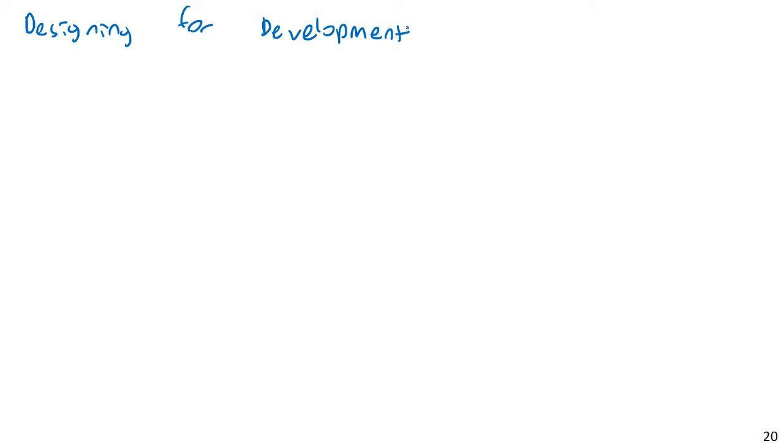We're going to spend most of our time talking about tension reinforcement development length, but you also have development length for compression reinforcement, which is what you sometimes have for members where the concrete itself doesn't give enough compressive strength, and you need to add a little extra, and so you add compression reinforcement.